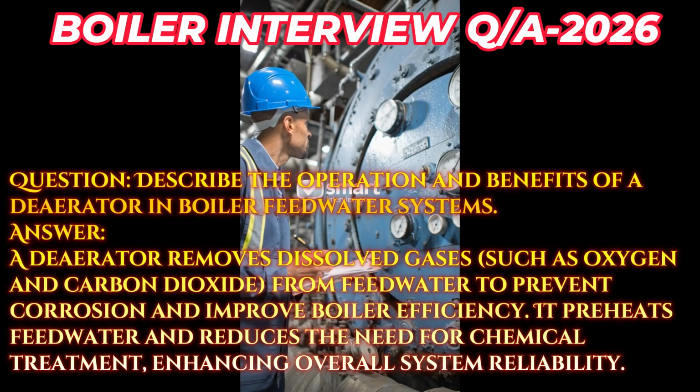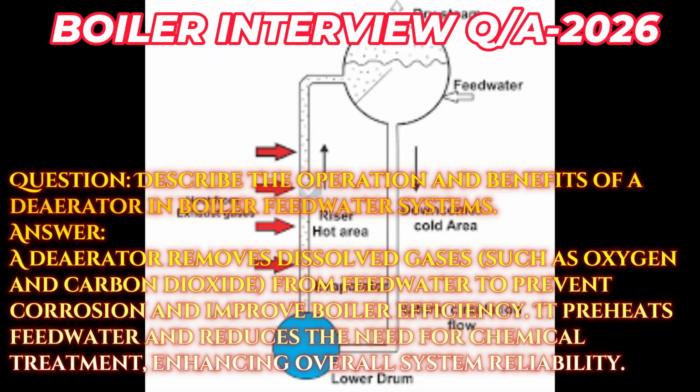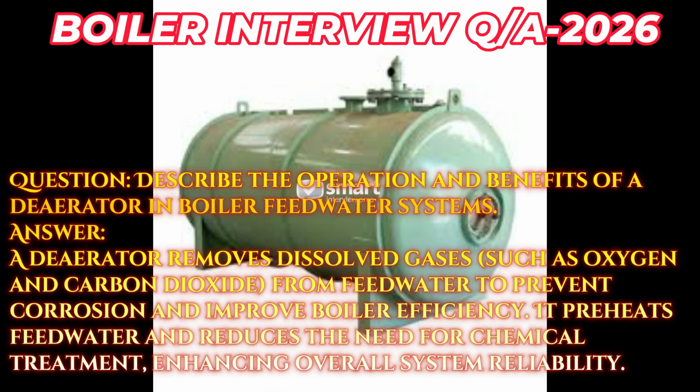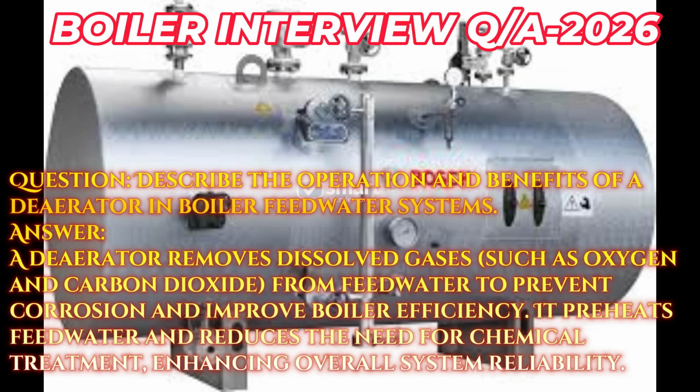Question. Describe the operation and benefits of a deaerator in boiler feedwater systems. Answer. A deaerator removes dissolved gases, such as oxygen and carbon dioxide, from feedwater to prevent corrosion and improve boiler efficiency. It preheats feedwater and reduces the need for chemical treatment, enhancing overall system reliability.